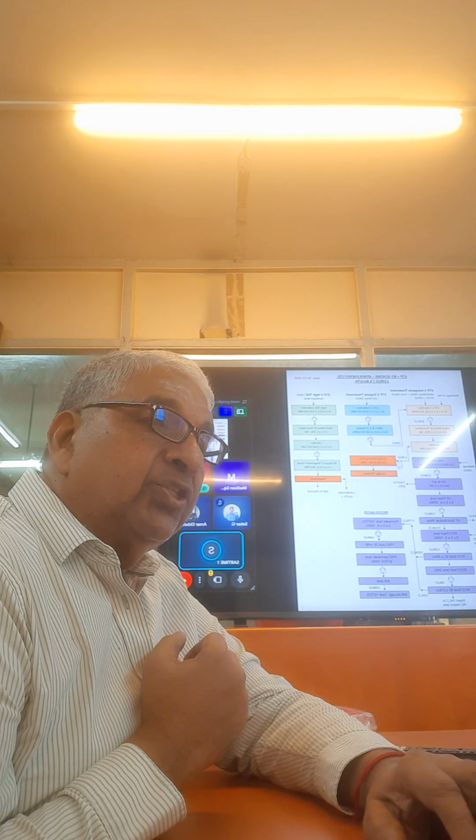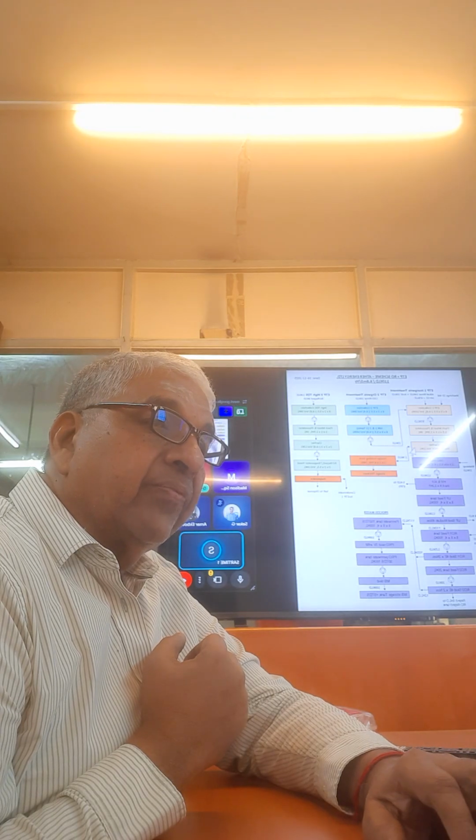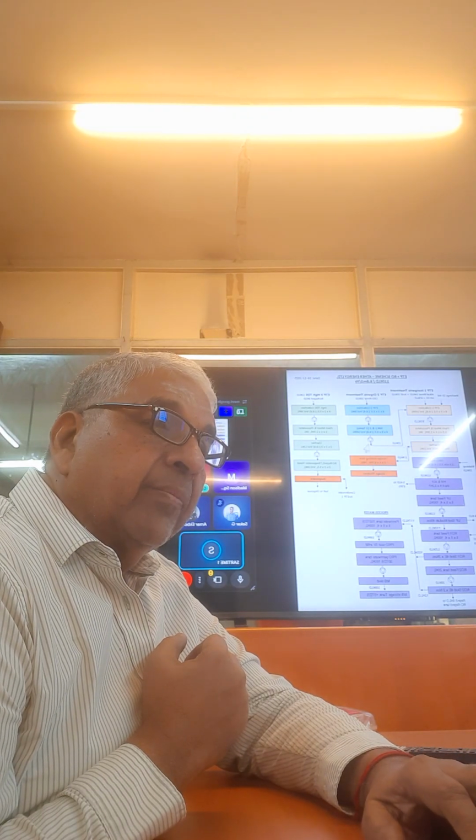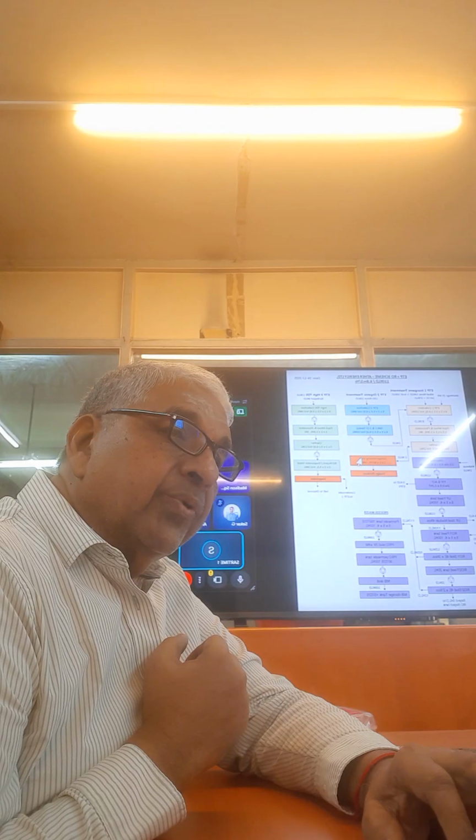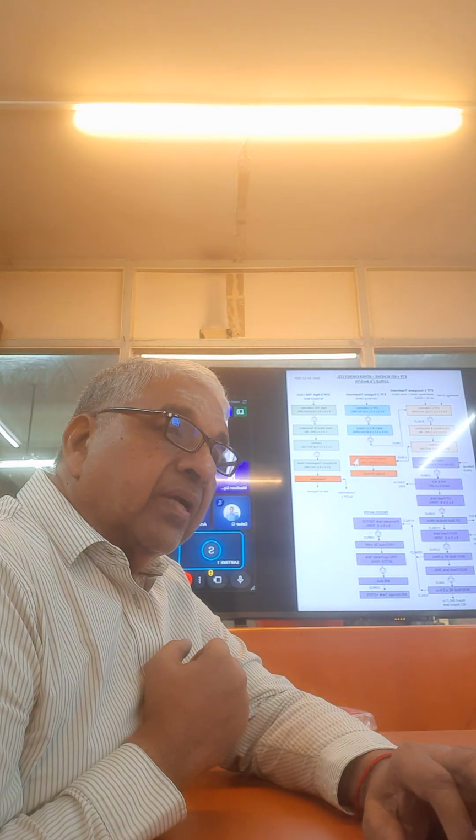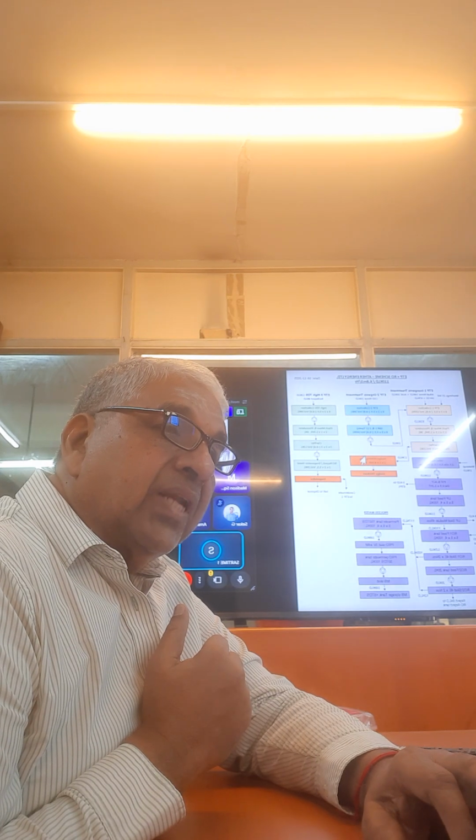Okay. Now the sludge comes from the clarifier, from the SBR. I didn't put the marking here. This clarifier will come to the thickener. I have to put the marking. I have modified another drawing, but only this drawing I have right now anyway. This clarifier will feed here. The clarifier underflow from the high TDS will come here. Everything will come to a sludge holding tank.